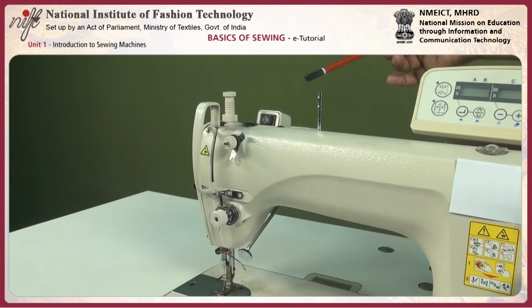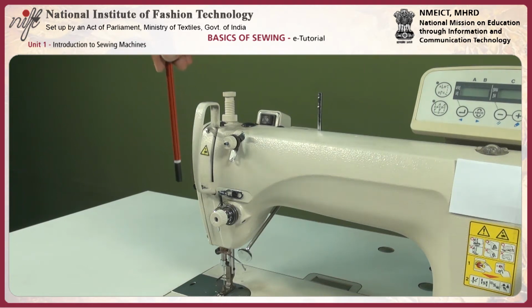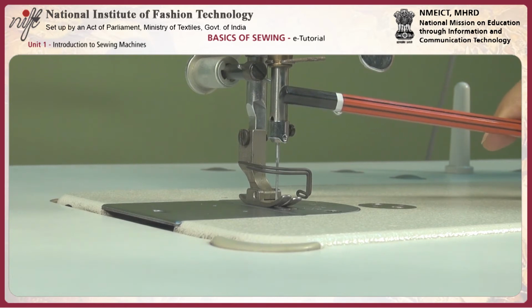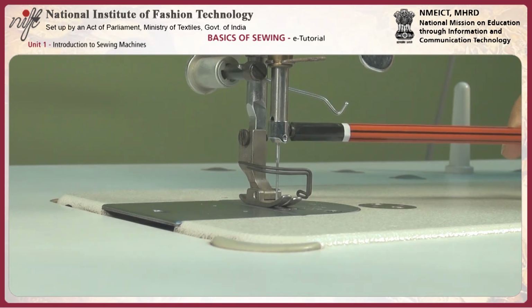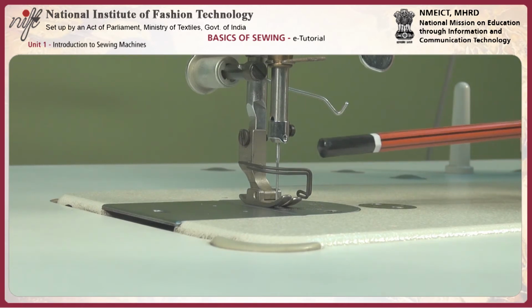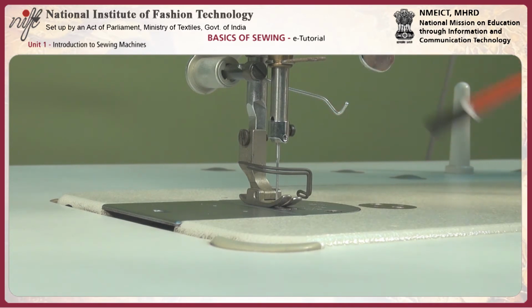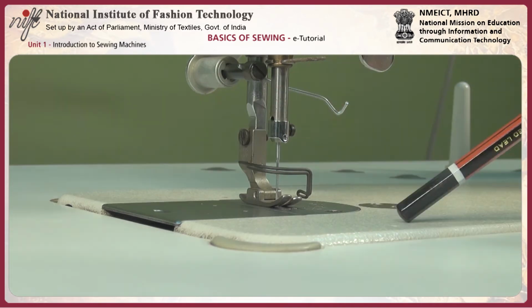This one is a thread guide. This is the thread guide. One more thread guide is there, and this is the thread tension assembly and thread take-up lever. This one is a face guide. One more thread guide passes the thread to the needle. Needle bar, needle tighten screw, needle, finger guard, pressure foot bar, pressure foot tighten screw.